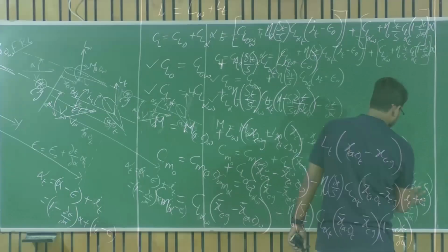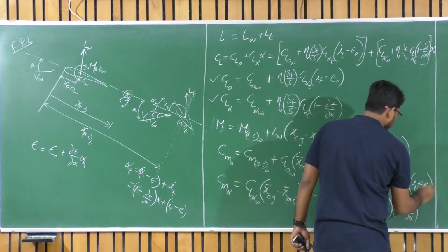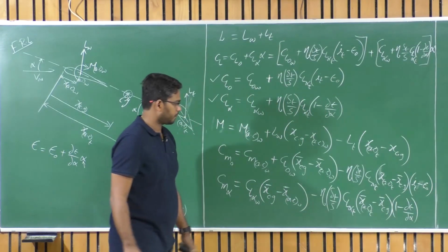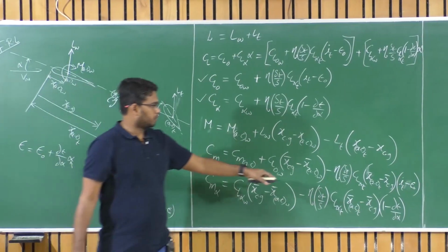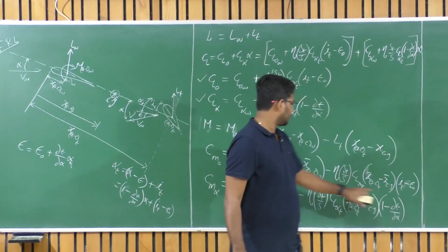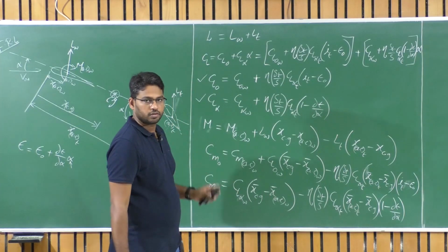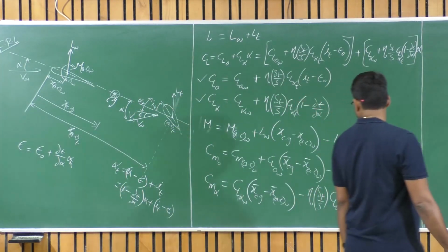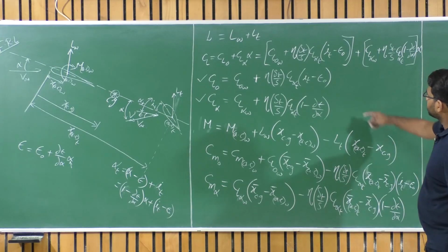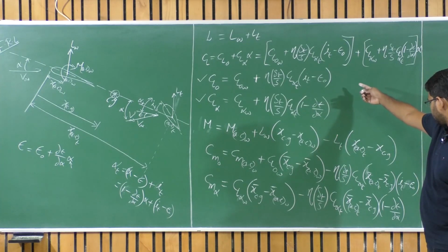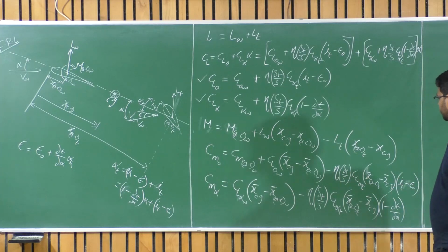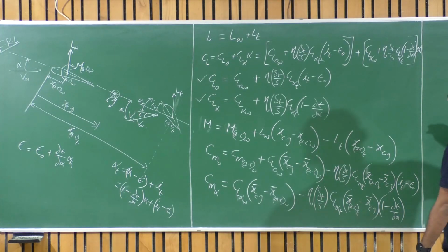Okay. Yeah, please correct this. This should be minus epsilon naught. So it has to be. So it contributes towards positive. When I of t is negative, this contributes towards positive value here. Right. So this is CL naught, the same thing, right? It is from the CL naught itself, I of t minus epsilon naught, but it is giving pitch down moment, that is minus of that, right?